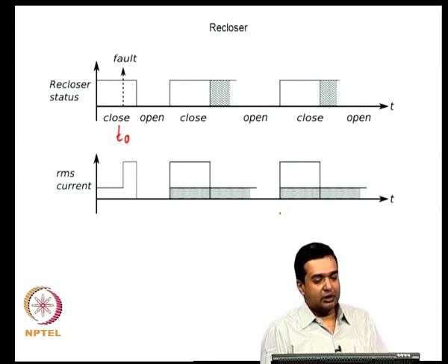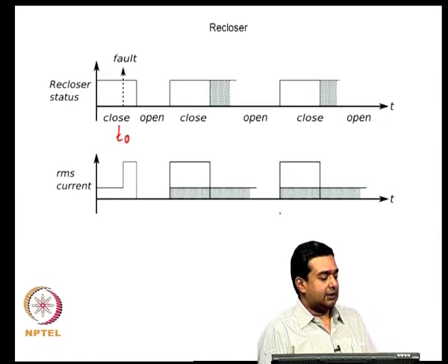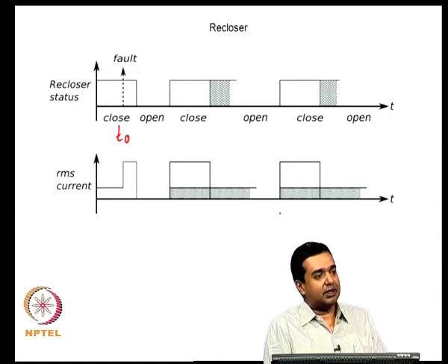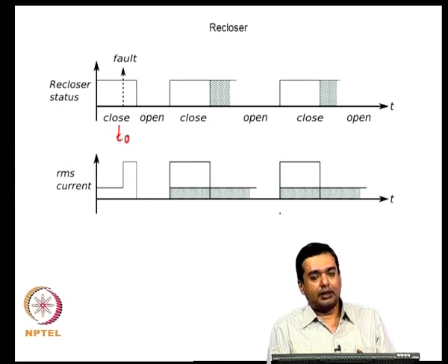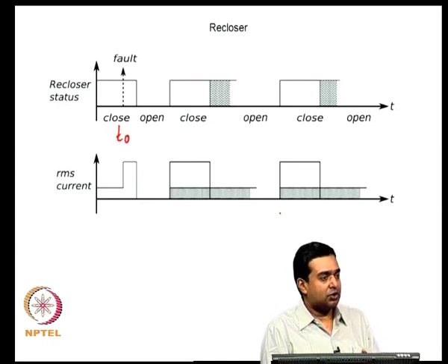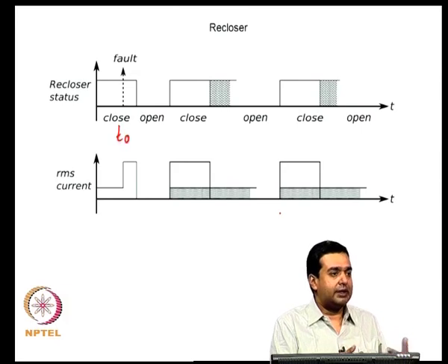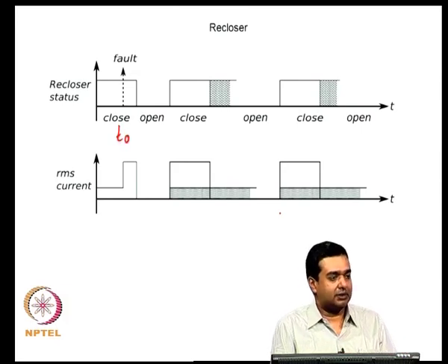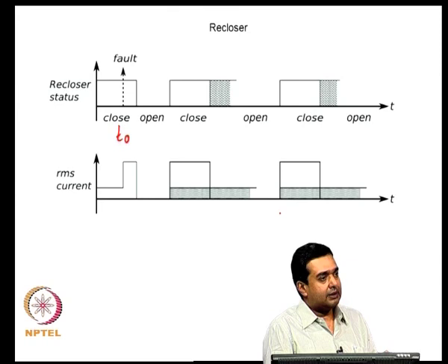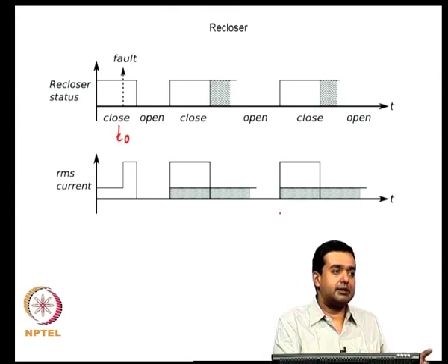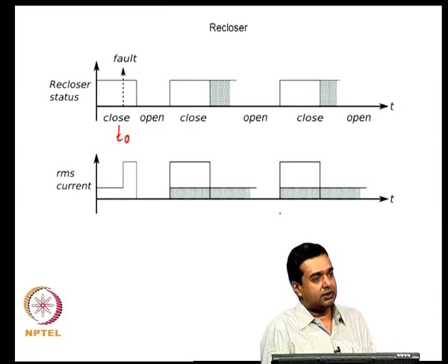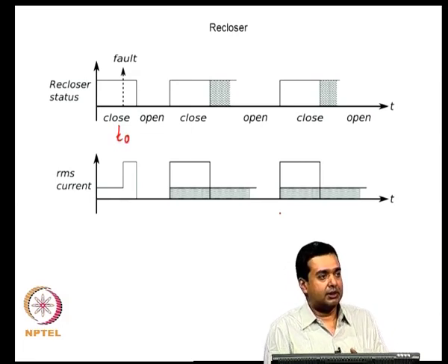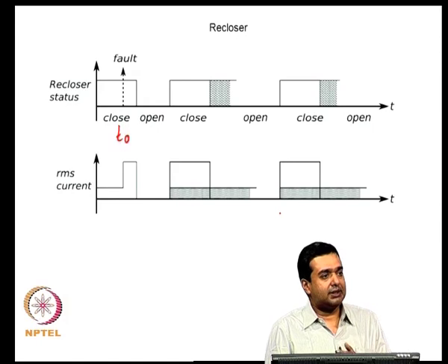So, if you think about the recloser, it can be thought of as a circuit breaker, and the circuit breaker might have its own time over current characteristics, and the circuit breaker might also have a program to execute this reclose action. And if you already have relays in the substation, you can now incorporate this reclose logic along with the feeder circuit breakers sitting at the substation.